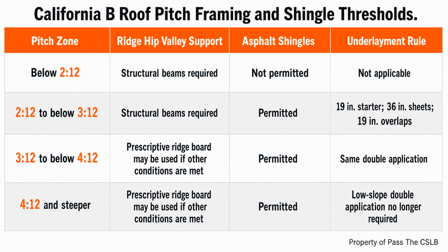The supported effect behind the low slope threshold is increased outward thrust as the roof becomes shallower. If a contractor substitutes a thin ridge board where a structural beam is required, the problem is not cured by adding nails and hoping the sheathing makes everything act together. The load path, shown on the plans, still has to reach proper vertical supports. That is why I treat a low slope ridge detail as an early coordination item, not a late framing inspection